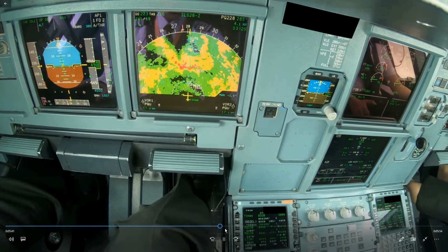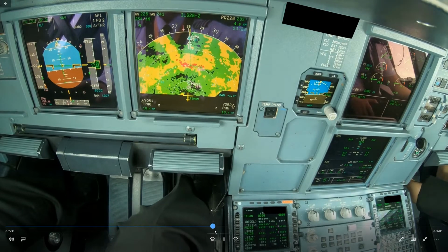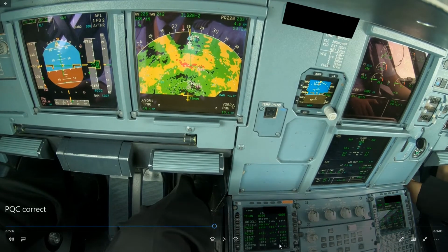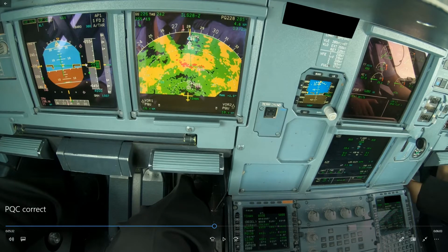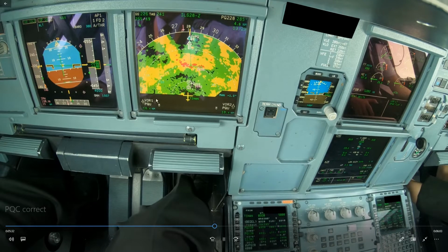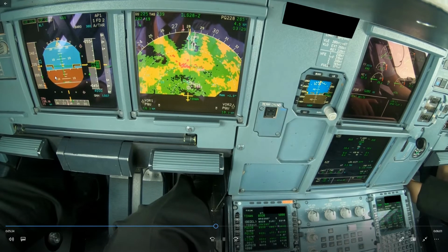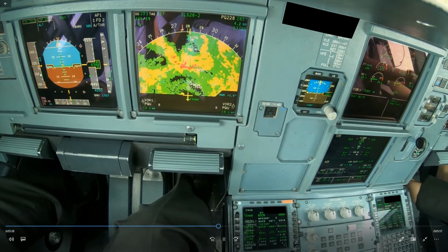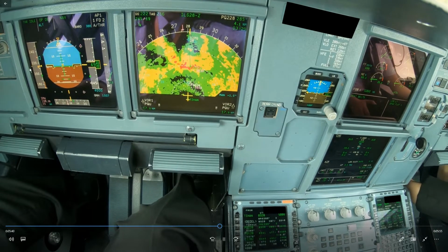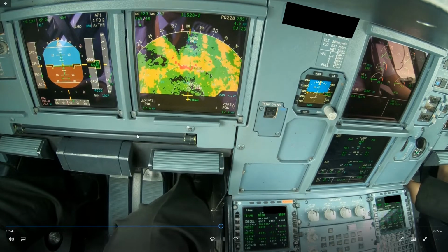Okay, so if I backtrack a little bit, we can do an altitude calculation or a profile calculation. So at the moment we are exactly at 20 miles. The speed is near green dot, so 20 times 3 is 6,000 feet, minus 1,000 feet to slow down is 5,000 feet. And we're exactly at 5,000 feet, so we are on profile. In this case, you could elect to just keep the speed because you're on profile anyway. But anyway, I decided here to increase the speed a little bit.